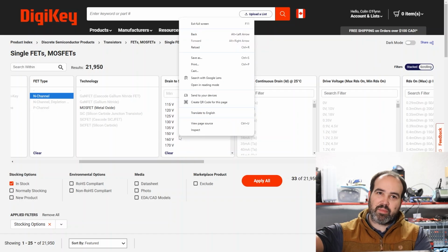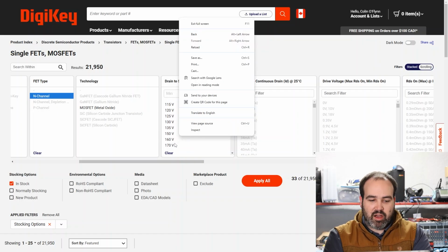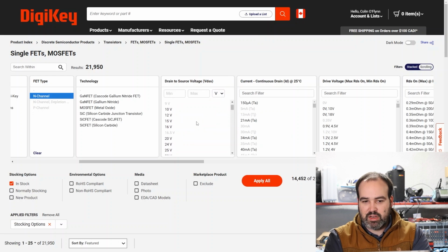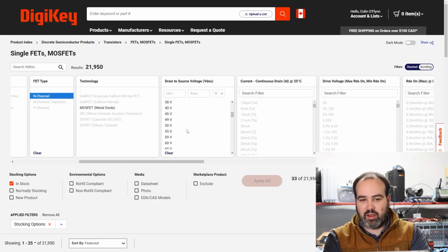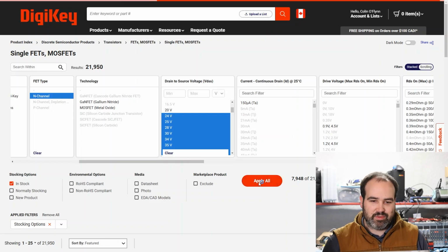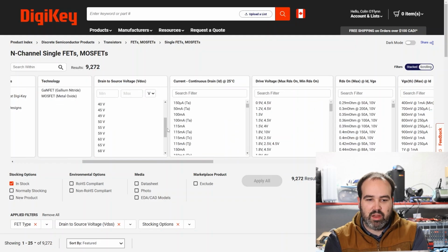As the voltage goes up, right, the cost of the MOSFET is going to go up as well. For a given MOSFET, if I have a 100 volt MOSFET, it probably will have a lower current handling capacity than a 24 volt MOSFET. So we don't want to go too high, so I might go into the 24 to 100 range. For this design, this is very straightforward, so I'm not too worried about that.